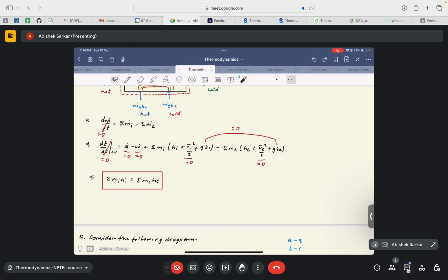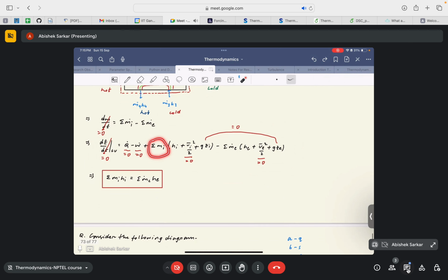I also thought that if we consider the fluid to be inviscid, then we can disregard the viscous dissipation term. But here the viscous dissipation term, or the term that is associated with the heat generation in the case of viscous fluids, is also taken into consideration within this framework. And moreover, the change in density of the fluid is also not imposed, because we have not told that the density of the fluid has to remain constant. We have not discussed it while deriving the equation.